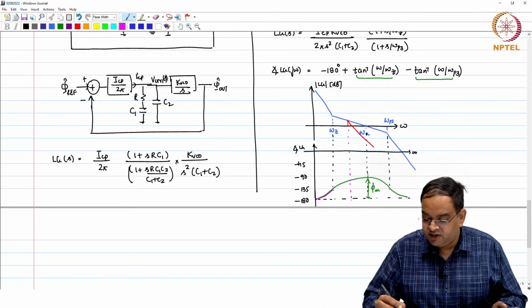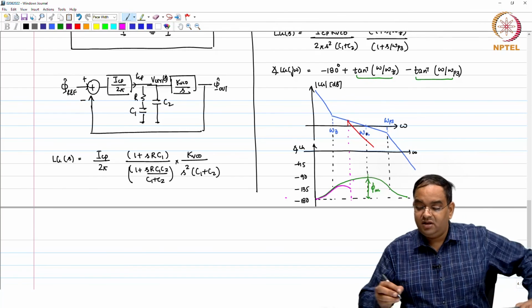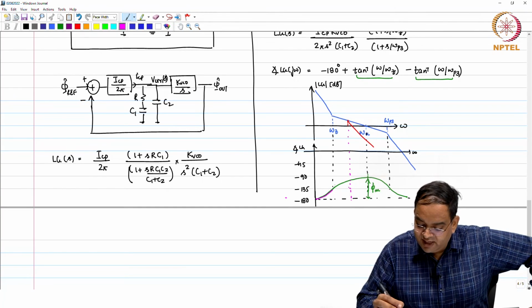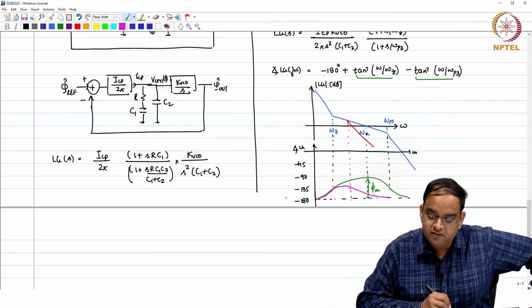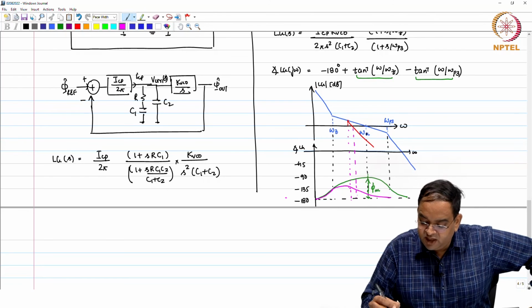So, before it reaches, your frequency comes, it does not reach minus 135, does not reach minus 90 degree. So, what you may see is the phase is actually much lesser, right. It is not going to be minus 135, it will be slightly larger than maybe minus 135, and then it will finally go like this. So, these are the two cases which I have seen, and if you now want to calculate the phase margin, it is going to be only this much.